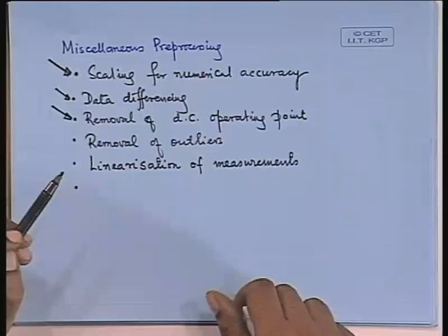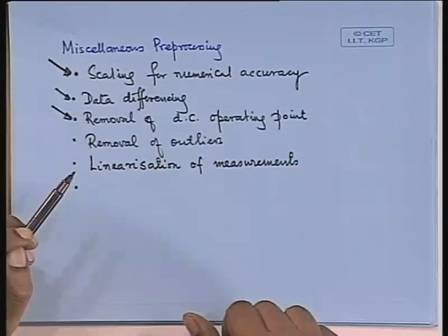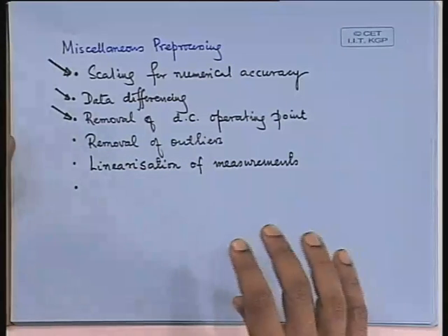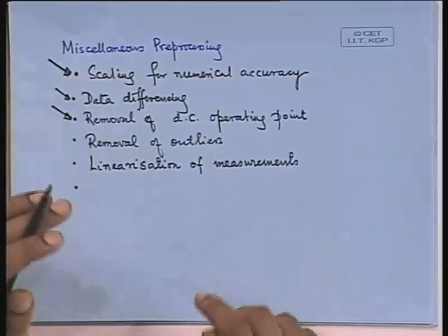The advantage is that if u or y had any DC bias, that will go off, because the same DC will get subtracted. Similarly, you might have to do that if you are using a linearized model, because a linearized model, by definition, is a model between delta y and delta u, where you have to measure the delta from the operating points. So there is a u0, there is a y0, and your model is always between y minus y0 and u minus u0, right? That is the model in the linearized model. So you might like to do that.